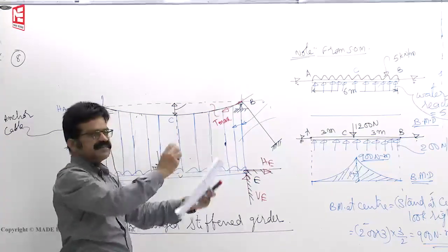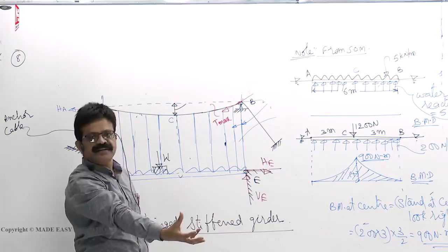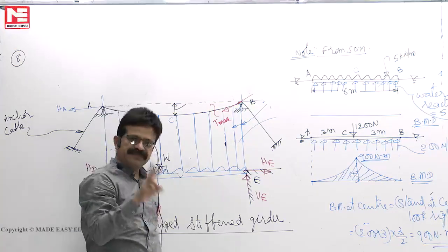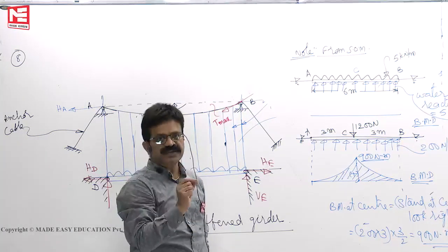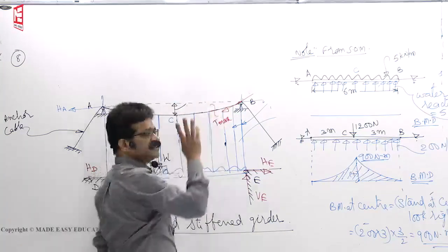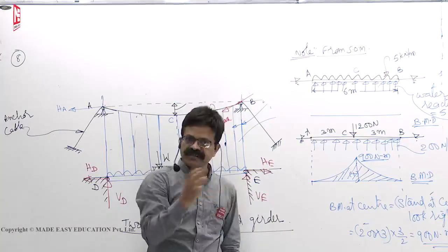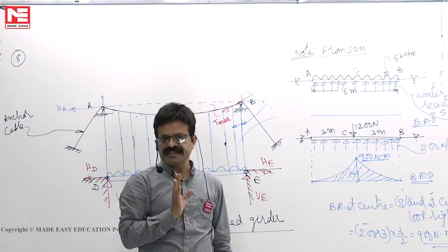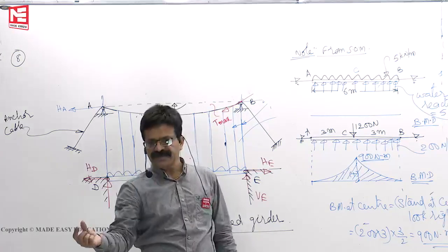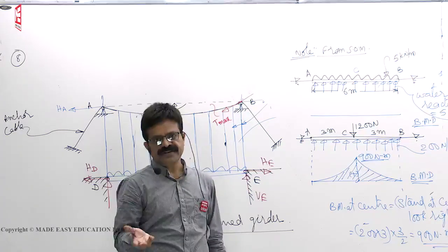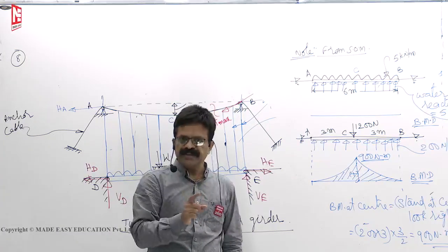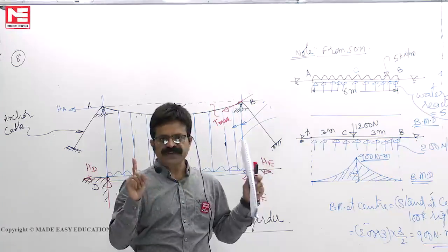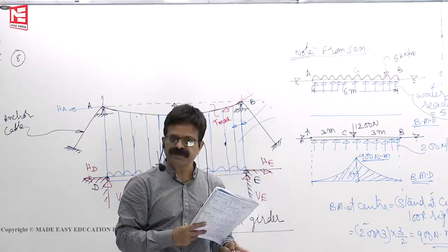If you reverse it and build a structure, then you will get two-hinged arches or three-hinged arches. For a two-hinged arch, remember that the edges must be hinges. If a two-hinged or three-hinged arch is subjected to UDL throughout its length, then that arch will become a linear arch or theoretical arch, because the arch takes the shape of the bending moment diagram of an imaginary simply supported beam.